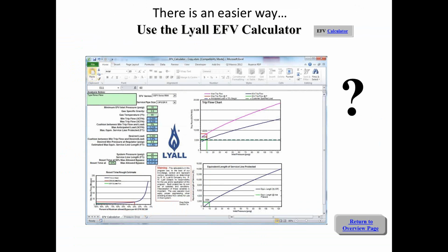If you're looking at branch services where you have two structures that have particular loads, each of them have their own expected loads, you obviously have to design the trunk portion of that service, or what would be the main or pre-branch portion of that service, to be able to handle the length with the pressure drop.